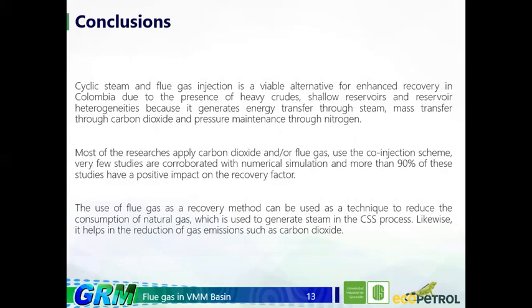So the last one, the use of flue gas as a recovery method could be used as a technique to reduce the consumption of natural gas, which is used to generate the steam in the CSS process, that is cyclic steam stimulation. Likewise, it will help in the reduction of gas emissions such as carbon dioxide too.